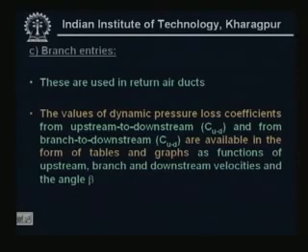So once you know, for these three types of fittings, that is bends, branch takeoff and branch entry, the important thing is to find out the dynamic loss coefficient. Okay, once you know the dynamic loss coefficient, and if you also know either the velocities or the flow rates and the duct dimensions, then you can find out the dynamic pressure loss because of the fittings, right.